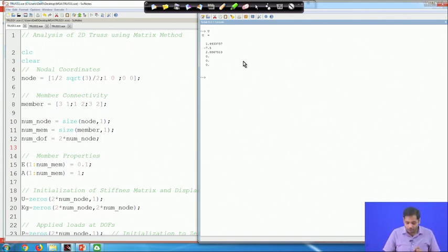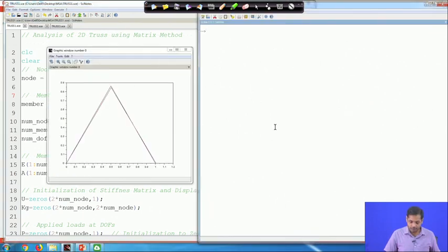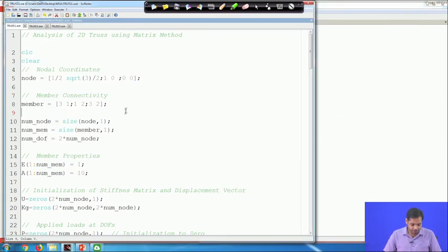Okay. Now, which is very obvious because it is a linear problem, the force displacement is really linear. So, if you change linearly the Young's modulus, the effect on the displacement will be linear. If you increase the Young's modulus, the displacement will decrease, and if you decrease the Young's modulus, the displacement will increase. And the same thing we have here as well. If we change the area, then let us see what happens. This will be your u. Okay. So, it is decreased by 10 times. Okay. So, this was obvious, right.